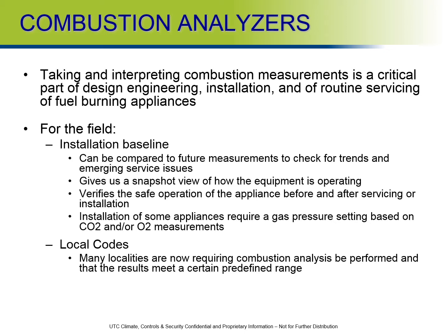But first, let's talk about combustion analyzers. Taking measurements on installation and during startup procedures creates a comparative baseline for operation of the equipment. Okay, so you'll be able to use this information against future measurements to check for any kind of trends or possible emerging service issues. All right, it's also going to verify the safe operation of the unit or appliance.